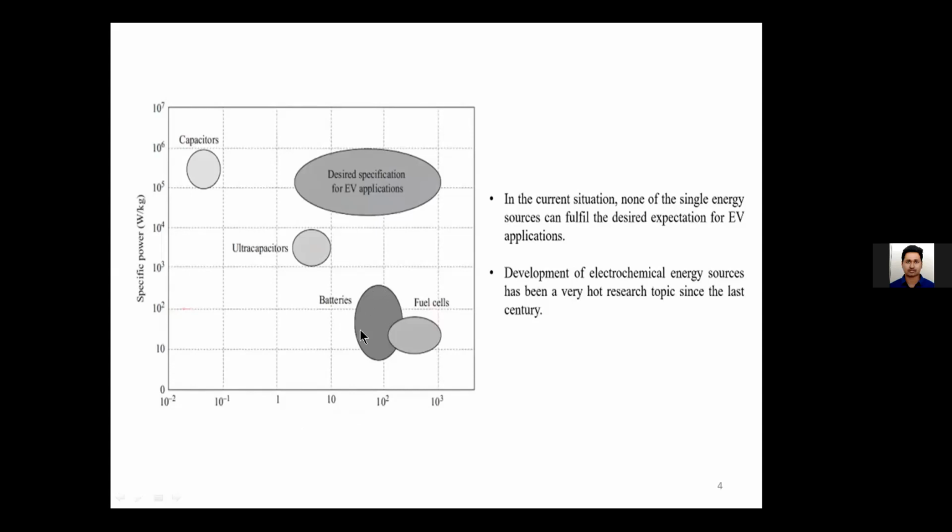So here, battery you can observe, even though it has better energy density, the specific power is somewhat low. Among the various sources, here are batteries, we have ultra capacitor here, and capacitor something around here. So the power density is relatively low when you come to a battery, even though the energy density is sufficiently good. Due to this particular reason, the amount of weight required by the battery for vehicle applications is very high when you compare with the fossil fuels. So this is one such limitation.